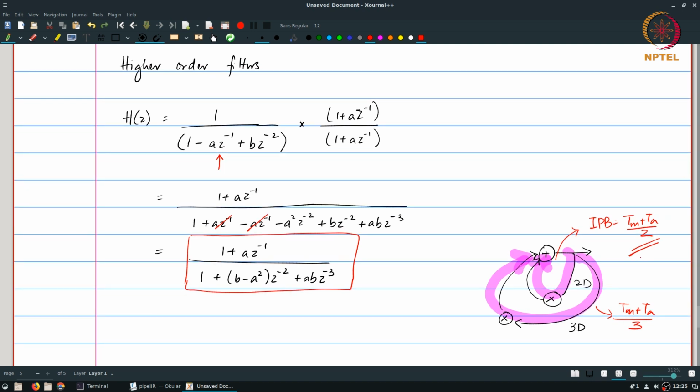So the purpose of this was to show that there are certain kinds of situations in which we can actually make fundamental changes to the structure of the architecture that we get for a signal processing algorithm. The iteration period bound that was derived is something quite fundamental and is not to be taken lightly. It does set fundamental limits on the best sample period or sample interval that can be used for the system. Changing that is not possible through the regular manipulations or transformations. Pipelining, parallelism, all of those always respect the iteration period bound and do not try to change it.